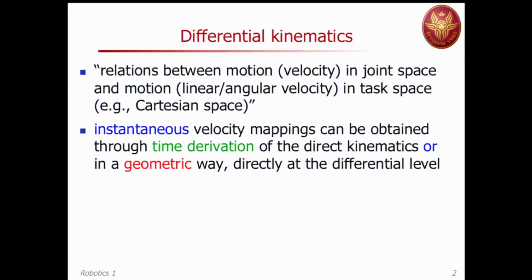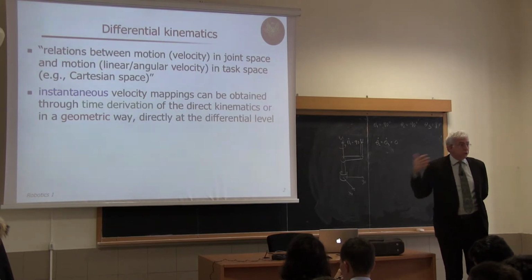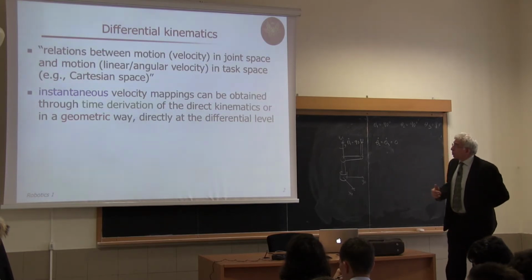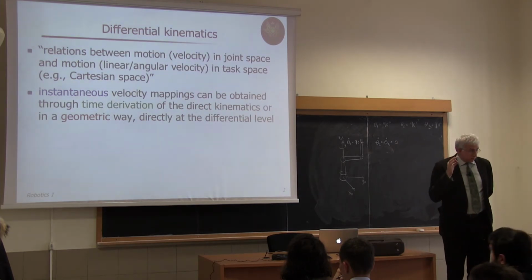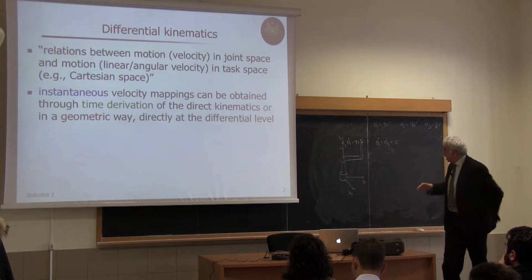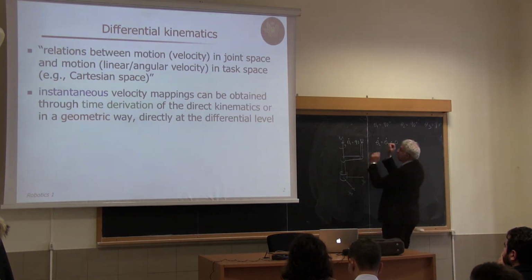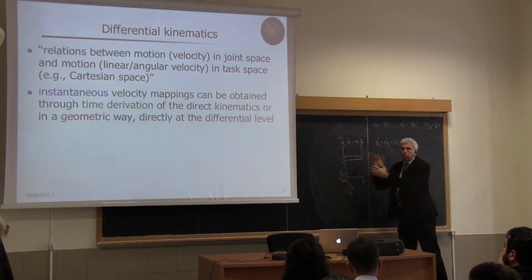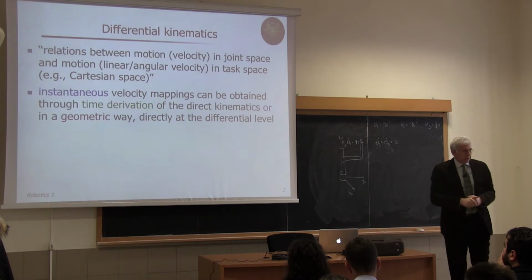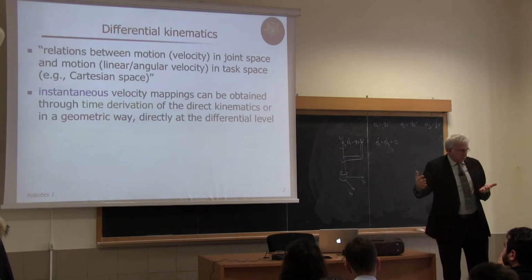So, remember, let's talk about velocity, but have in mind in the background that the same thing will apply to acceleration or to the third derivative with respect to time, which is called jerk, and so on and so on. But what we want to do is to compute this instantaneous velocity. This is why I'm saying I'm freezing the configuration and I'm computing this. Then I'm applying the velocity and the robot will change configuration, and then I repeat this. So it's a continuous process.